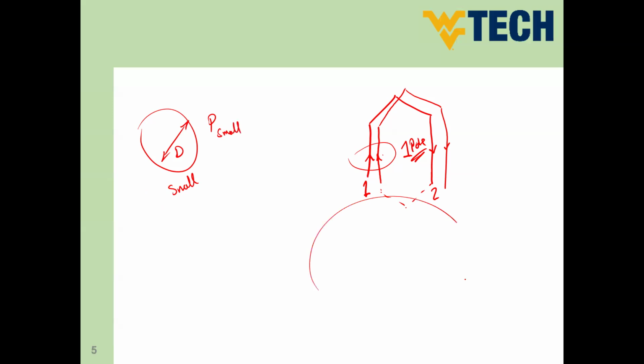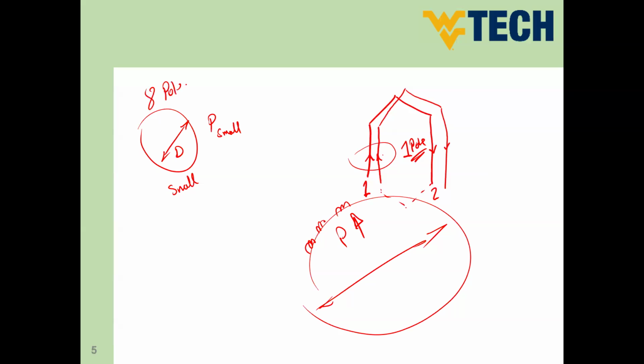However, for a large diameter salient pole, this gives us the opportunity to make windings in different poles. So the number of poles here is going to be large. For instance, you can find cylindrical poles up to 8 poles because we don't have a large diameter. However, in salient pole, you can have up to 80 poles. So it's 10 times more.